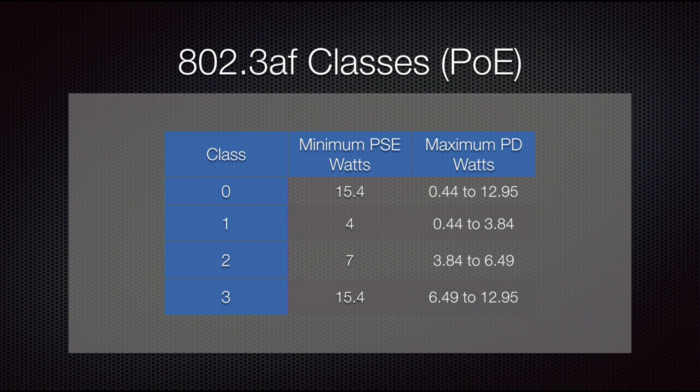Now, it negotiates. So if you have a device that is class 2, for example a BirdDog device, I had a hard time finding this, but I sent a note to BirdDog and asked, are you 802.3af, at, etc.? They sent me back a note saying yes, they are 802.3af compliant, and they are class 2. The reason for that is that they operate under 7 watts. So when you plug in a BirdDog, it talks to the switch. The switch says, okay, what kind of device are you?